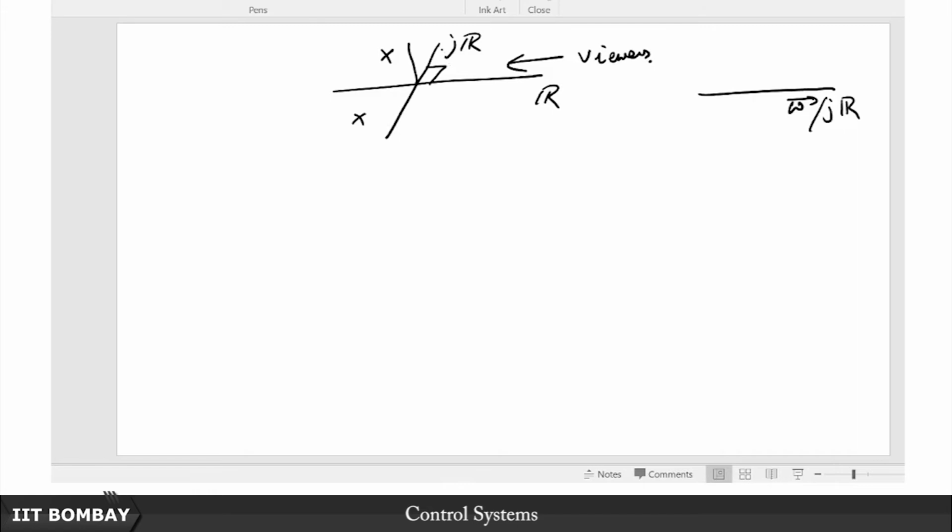See, earlier in the root locus case we were drawing this j-omega and this sigma, this plane, and we were sort of looking at it in this fashion. So, what we were looking at was this sigma and this j-omega, and you had this complex pole pair here. But now I am saying let me just flatten it out on the floor, and let us call this third axis, which is again perpendicular or orthogonal to both of these other axes. So, this is orthogonal to both of these axes. This axis now is my 20 log of M(omega) axis.